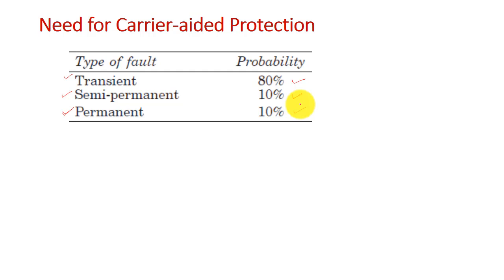It may be auto reclosure, or it is reclosed manually, right? Then if the reclosing is not sustained and it opens again because of the existence of the fault, it is considered a permanent fault and the circuit breaker remains open, right?